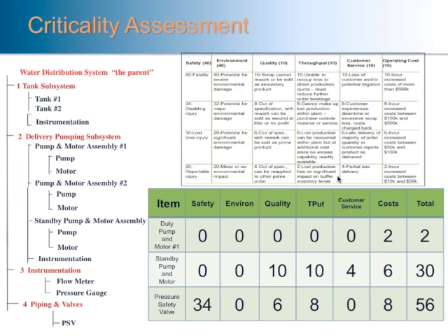The pressure safety valve shouldn't be of any surprise. We see that it has an enormous impact on health and safety, and because of the weighting, shows to be quite a large value. And there would be other impacts in production associated with the downtime through some kind of investigation. So this shouldn't be a huge surprise that out of that list of equipment, the most important or the most consequential equipment we have is the safety valve. It might be interesting to see what an enormous difference there is between the standby and duty. In a lot of places I visited, they tend to put heavy maintenance and reliability focus on the duty, and the standby can be somewhat ignored. So that's a complete reversal of what the situation should be.